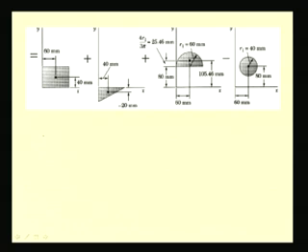So, we can write, let us say for the x axis, x bar A is equal to, if I say this is the area of the rectangle and I have the location of the centroid with respect to the y axis as 60 mm, so 60 times the area of the rectangle, which is 40 times 60, plus 40 times the area of the triangular lamina, plus